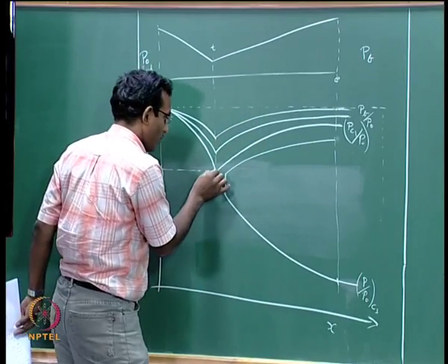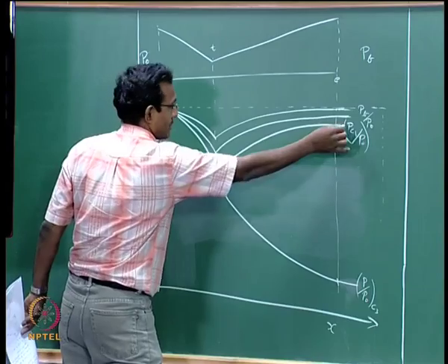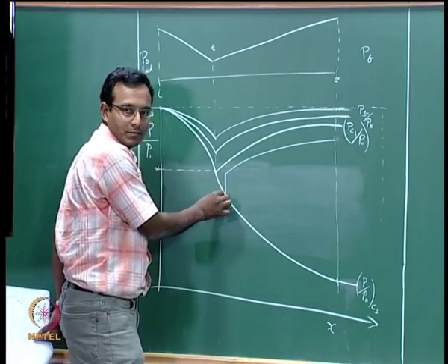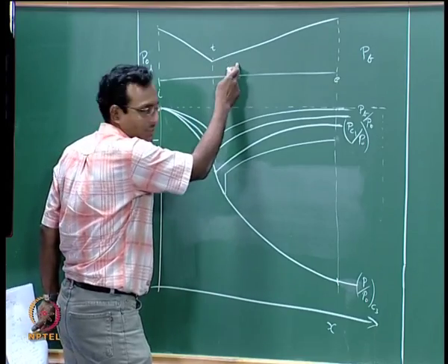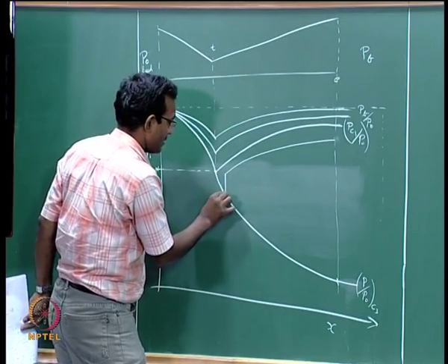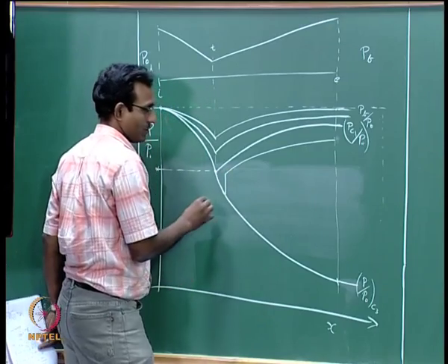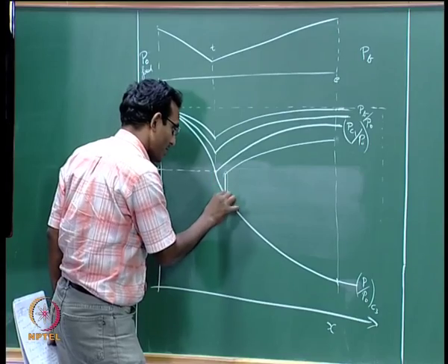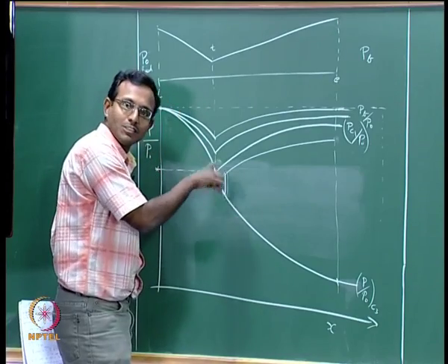Now, this is what the flow does. Once it is below critical pressure 1, it is going to take the supersonic path for some distance in this case, and then it is going to jump across to the subsonic solution using a shock, non-isentropic flow again. Only this one spot is non-isentropic really, just that one region.